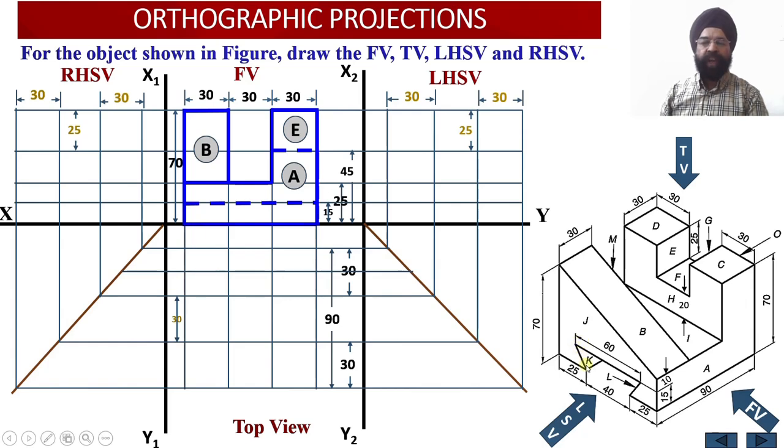So this angular portion is going to have the depth equal to 10 millimeter over here. Now let me see, I have drawn the first projection line at a distance of 15 millimeter from the rear side, and another projection line I have drawn at a distance of another 10 millimeter from this edge over here, so that the total distance from the rear edge becomes 25 millimeter.